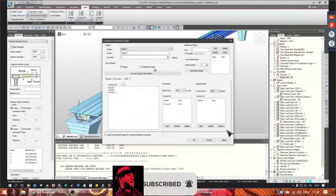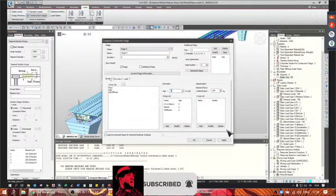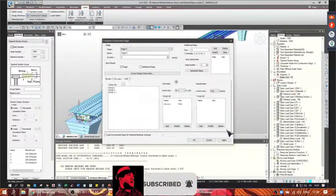In stage 0, we plan to cast the concrete of the slab. We have all metallic elements activated, also activating the links between the deck and the piers. The load activated is our group of load 1, including fluid concrete weight and the load due to workers.